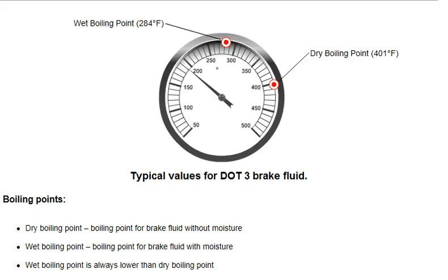Brake fluids inherently absorb moisture while in the hydraulic system. Because of this, two boiling points are listed for brake fluid. The dry boiling point indicates the boiling point of the brake fluid without moisture. The wet boiling point indicates the boiling point of brake fluid with moisture. The wet boiling point is always lower than the dry boiling point.